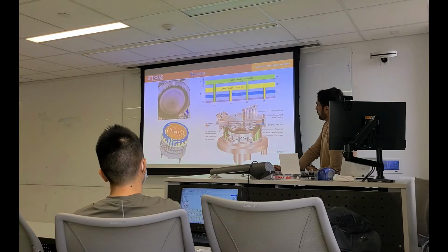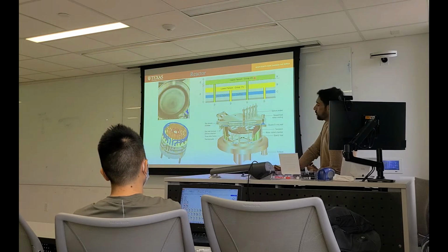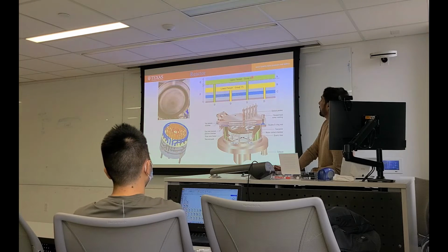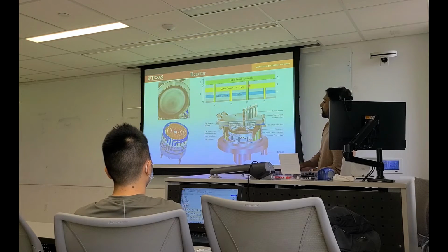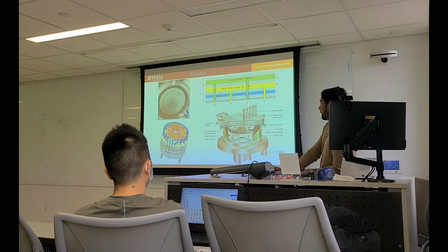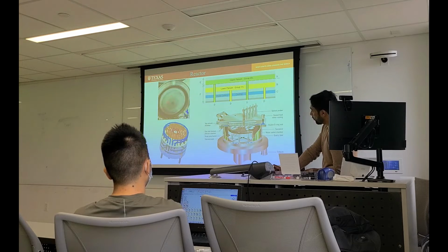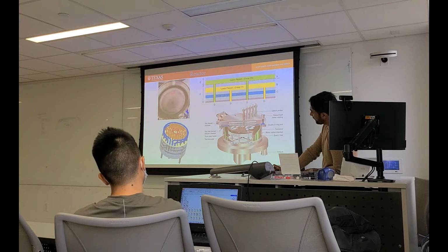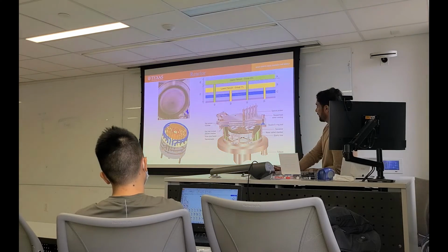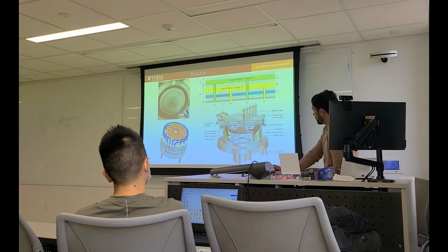It has two plenum chambers. The upper plenum, we use it for group 3 precursors. For gallium nitride, we can flow trimethyl gallium through this plenum. And the lower plenum is used for the group 5 precursors, depending on your compound semiconductor. You can see these very tiny holes, these tubes, they are throwing your precursors inside the reactor.